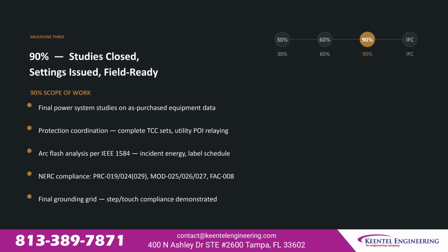NERC compliance covers PRC-019, PRC-024, MOD-025, MOD-026, MOD-027, and FAC-008. The final grounding grid demonstrates step and touch compliance.